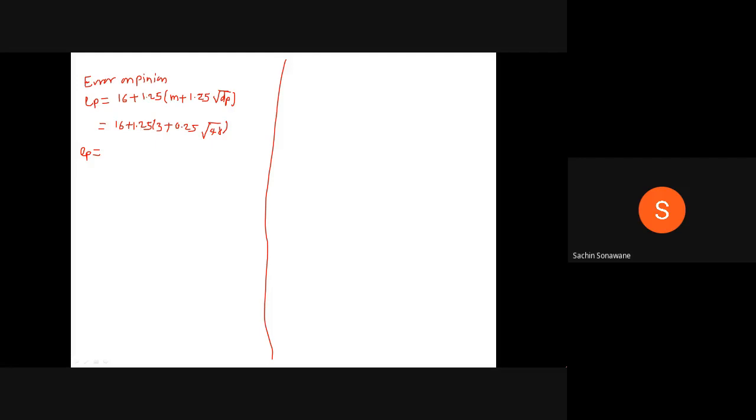Okay, I think you have calculated. Therefore, ep we are getting as 21.92 microns. Remember this value is in micron, which is equal to 0.2192 mm. Now similarly you calculate the error for the gear.